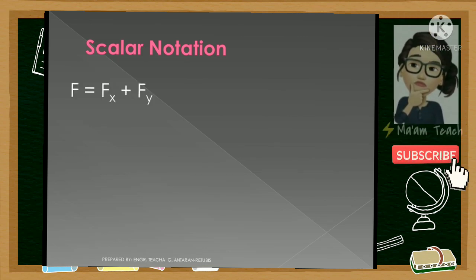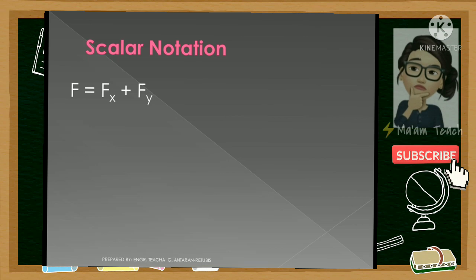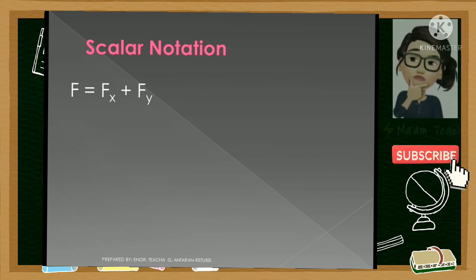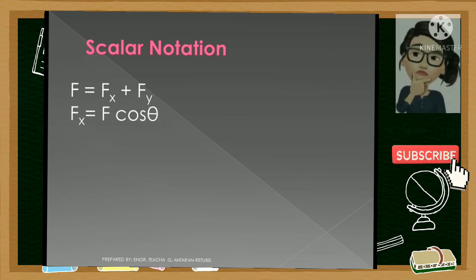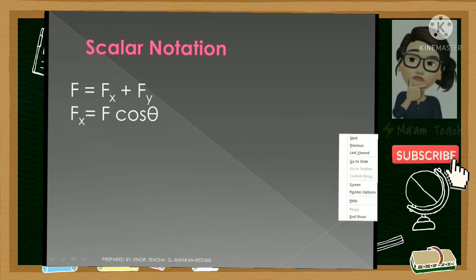Scalar notation, class, can be expressed like this, where your force is the sum of your x component and your y component. So your F sub x here is your x component, or your horizontal component, while your F sub y is the y component of your force, or your vertical component. So how are we going to get this F sub x, or the x component? You may solve that, class, by multiplying the magnitude of your F by the cosine of the angle that you have. Where did we get this formula?